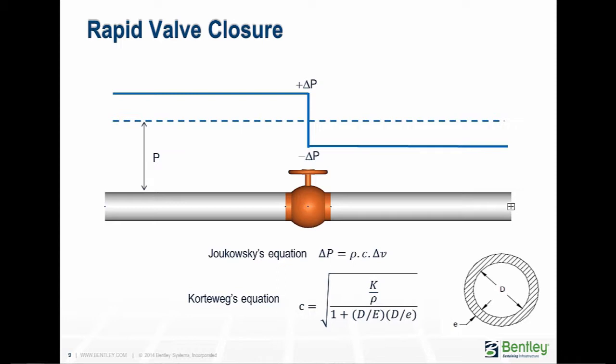Although commonly known as water hammer, the same effect can be witnessed in gas and steam lines. Because the bulk modulus and density are lower, the speed of sound is slower in gas or steam systems, typically for air at sea level around 4.3 times slower than in water.